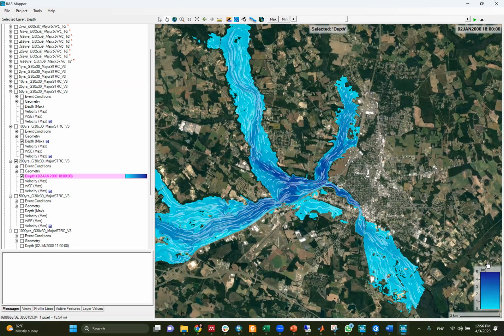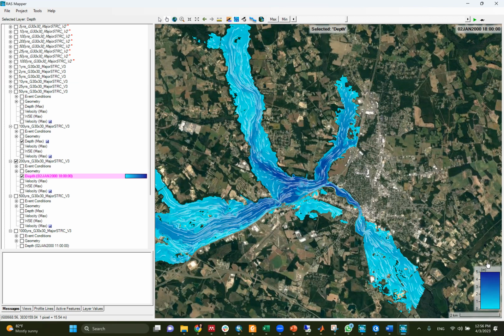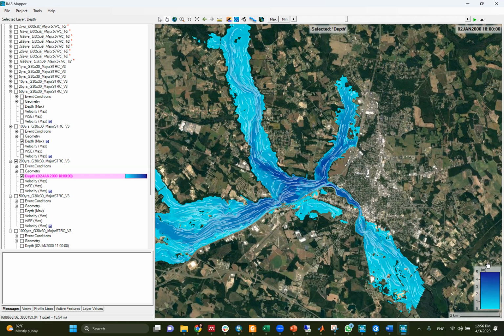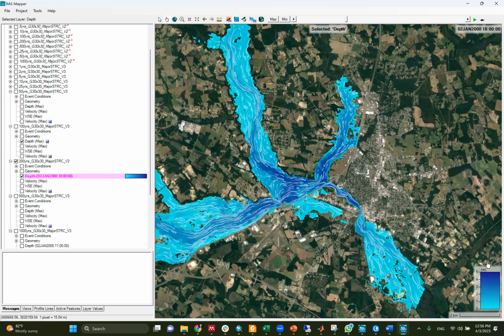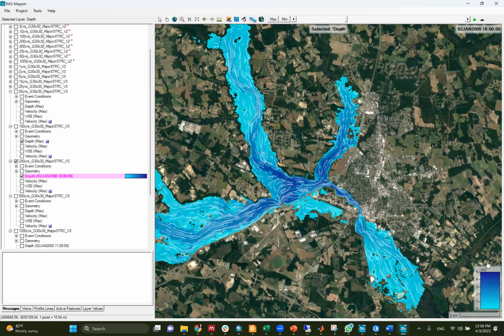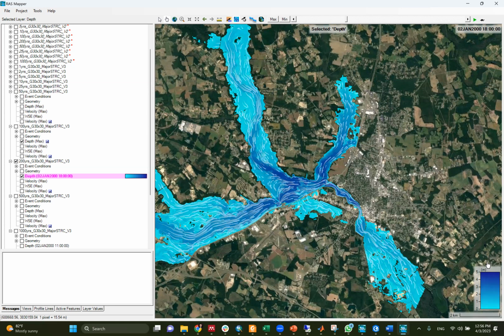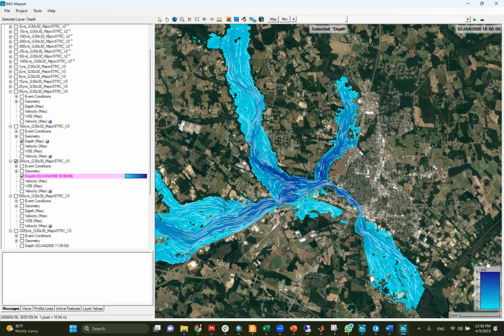Actually, this is a question that needs to be asked, but it will complicate the whole problem. If you put a flood barrier around every building, the flood depths will be going up because you are blocking these places. So if we want our models to be accurate, rather than saying in our model that if I put a flood barrier, I make an if statement, if the water depth is less than the barrier height, it will be 0, but if it's more than the barrier height, it will be the exact amount of losses.